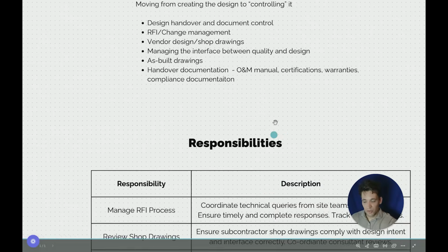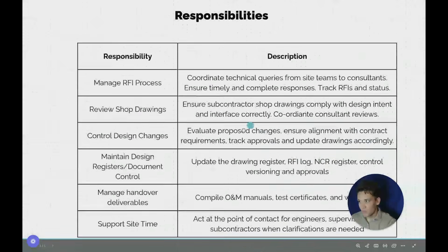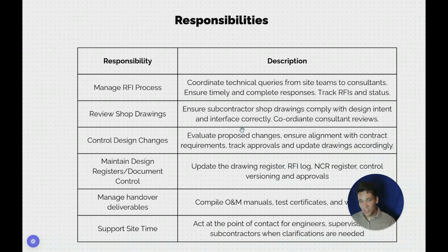So what are the responsibilities of the design manager during the construction phase? Well, they're going to be the one managing the RFI process. They're going to be coordinating closely with the construction teams to respond to technical queries from site teams to consultants, ensuring these responses are prepared quickly, on time, they're correct. They're also the one tracking the RFIs and making sure they get closed out.